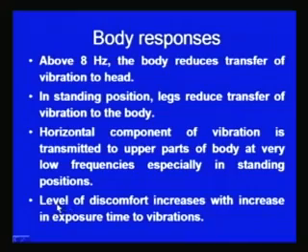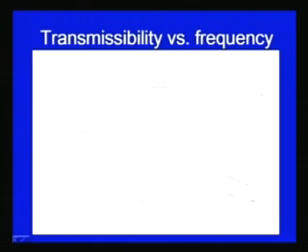You can see here that with the increase in frequency of the vibrations, their transmissibility decreases. For a person standing on legs, the transmissibility decreases with the increase in frequency. The same is true for the seat and cushioned chairs, where at higher frequency, the transmissibility of the vibrations decreases.